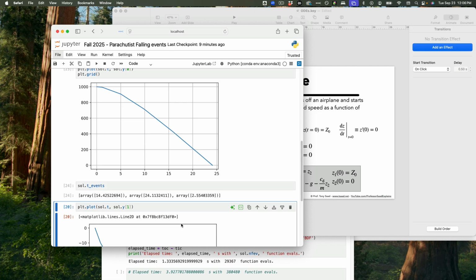Really, really cool. In my numerical methods, with ODE int, I used to give this homework and say, find the time, or like the friction factor or something. Find the location of where the friction factor is this much. This takes the guesswork out of it. It embeds a nonlinear solver into this. It's a really good detection tool. Events. Okay, don't forget about it.